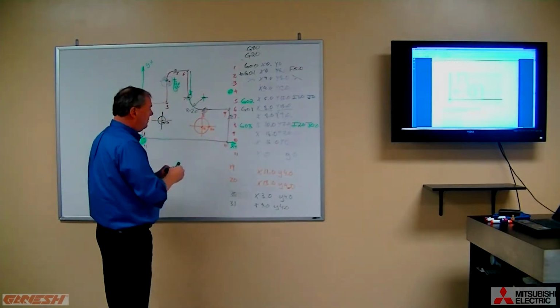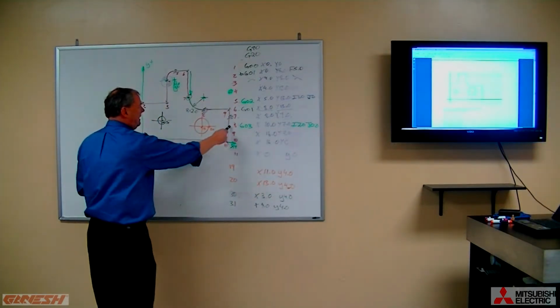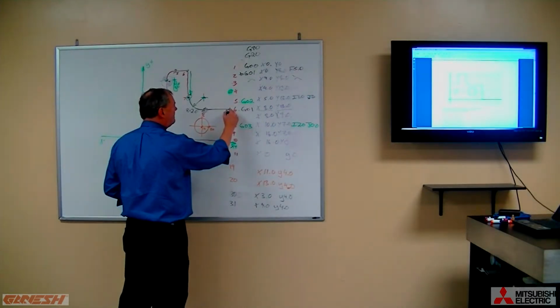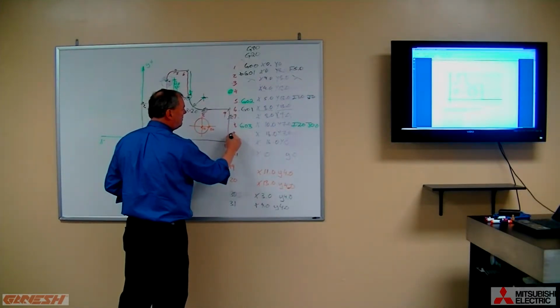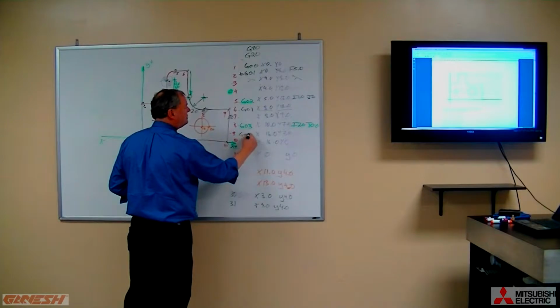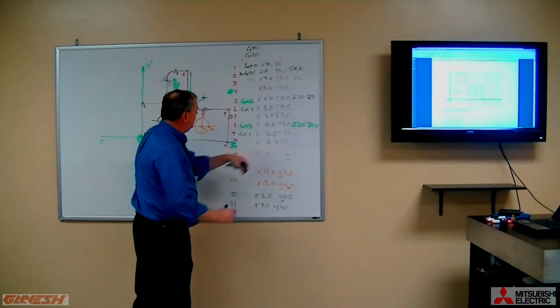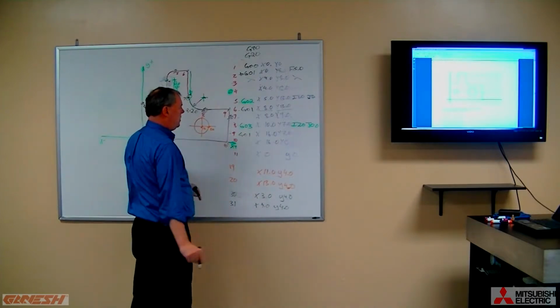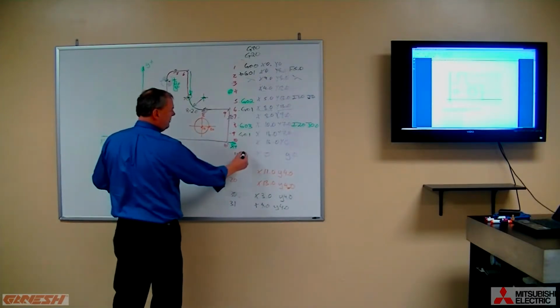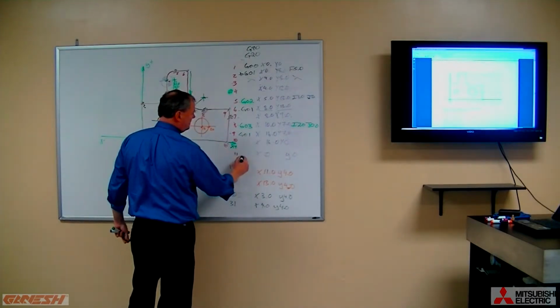So now we're sitting at point number 8, and we want to get to point number 9, and here is where we need to reestablish our G01. Then down to point number 10 is at X16, Y0, and then going back to X0, Y0.